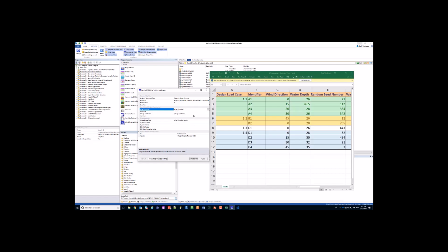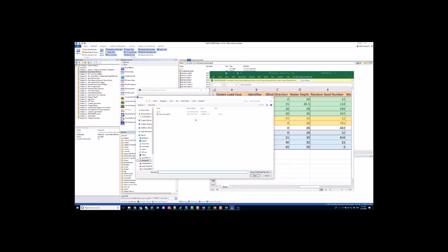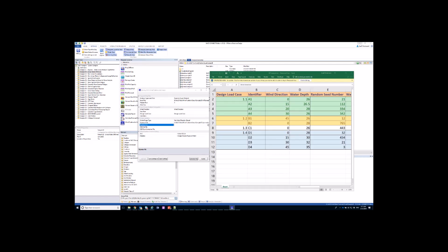Okay, so we have the design load case. We have some options in here too that are specific. We can do the mode shape type as either wind direction based or not wind direction based. I'm going to use not wind direction based here. It's also going to ask for some additional files. Here we have the dyne mode and dyne mass files that we need to previously generate from our dynamic modal extraction analysis, DynPack. So we'll select those files here.